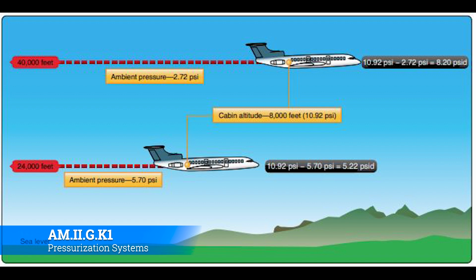So it's a fancy way to say essentially that you're simulating living and working at a certain altitude. Denver's about a mile high, so that's about 5,200 feet, give or take, depending on where you're at. So if you wanted to simulate Denver inside of the cabin in terms of air pressure, you would set the cabin altitude to 5,200. Even if the airplane is at 45,000 feet, the cabin altitude is going to be 5,200 feet, and it'll feel like you're living at 5,200 feet right there.